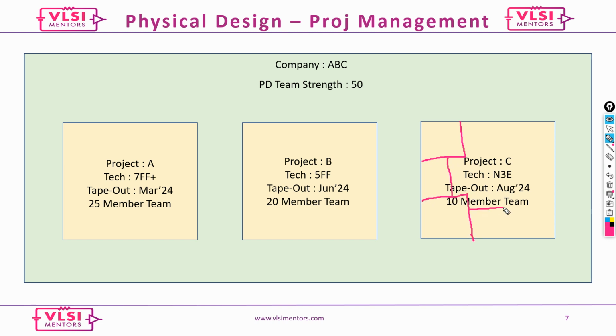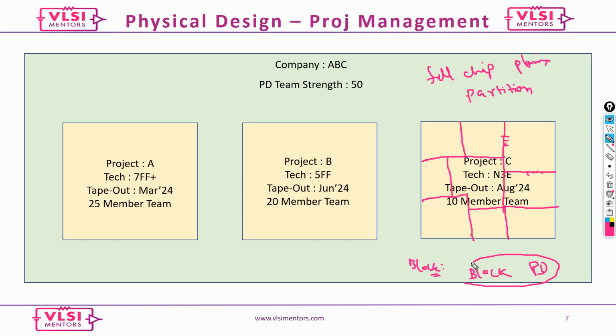So there would be a full chip person who would be doing this whole partition and all that information, and then they would say all these blocks. Say the first step is full chip planning. Now the partition, so they just give them the area and then the IO ports location and all that. Now the block owner takes that area and he builds, so block level PnR and PD. Now he goes and completes his block, implements the design.